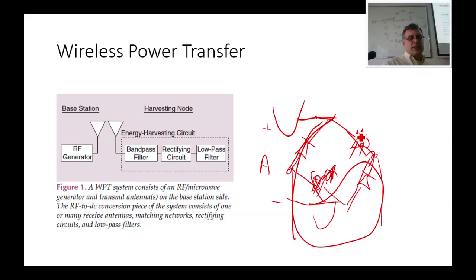Now, you're actually turning on 2 diodes per pass, which means instead of losing just 0.7 or whatever your threshold voltage is, you're losing 1.4 twice. And the problem is when you're dealing with socket power out of the wall, nobody cares. You can lose a little bit of voltage like that and still have very efficient transformation, because this is probably 10 or 15 or 20 volts coming through here.